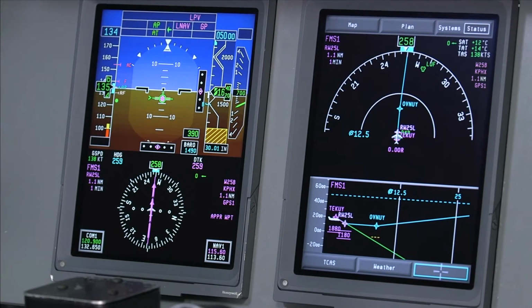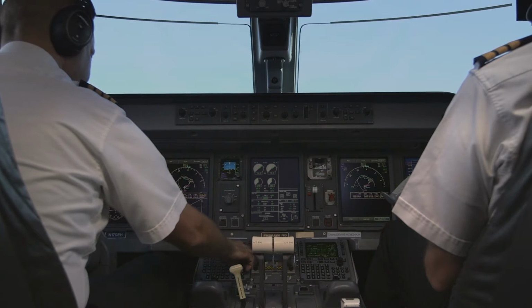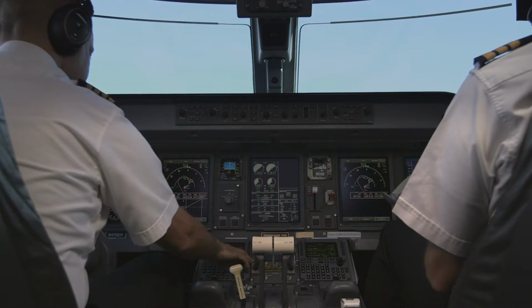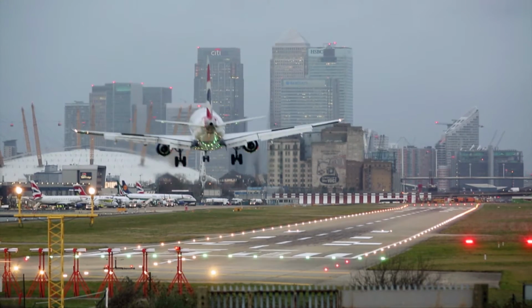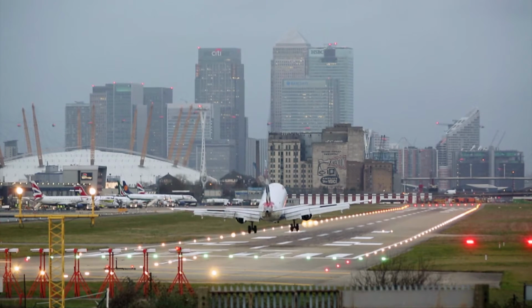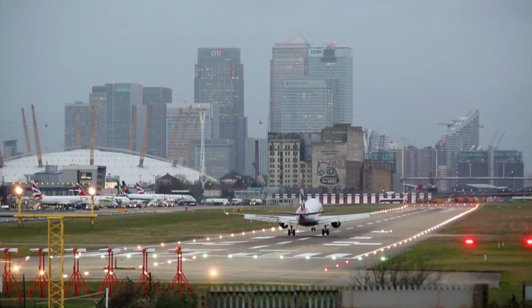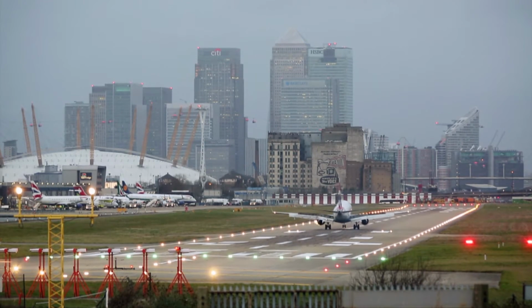The GPS receiver combines the SBAS correction signals with data from GPS satellites and produces highly accurate position data that is then used to fly RNAV approaches to LPV minimums. Prior to the development of SBAS, GPS was not able to provide the accuracy or integrity to achieve Cat 1 minimums during approaches.